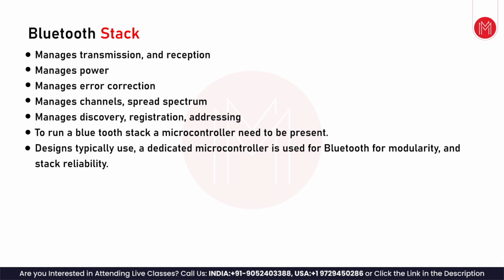A Bluetooth module is typically a dedicated microcontroller based module. It manages the Bluetooth stack. The Bluetooth stack manages transmission and reception, power, error correction, and many software activities like managing the channels, spread spectrum, discovery, registration, addressing, and all these activities. The Bluetooth stack does it. So to run a Bluetooth stack, a microcontroller is needed because of this software functionality that is implemented. A microcontroller needs to be present.